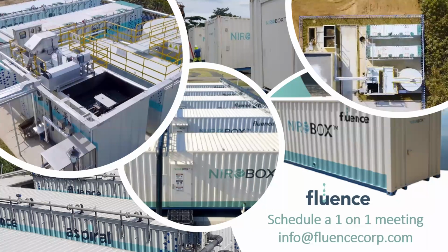So there's just a certain distance you can go by gravity, and then you reach the pumping station or lift station, from where it's a completely different story, usually higher flows, and this is the more expensive part of the piping.